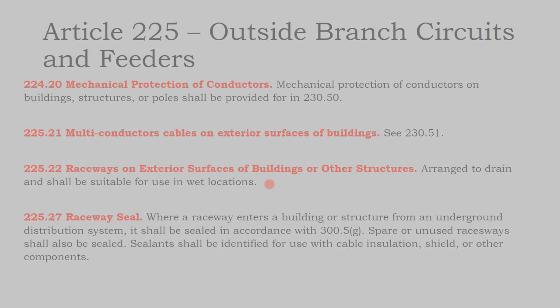What happened in this case was a heavy rain is when they noticed the water coming into the rooftop, and the contractor had not sealed the inside of the conduit. And so the water was pouring down into the box and actually getting up into the box.